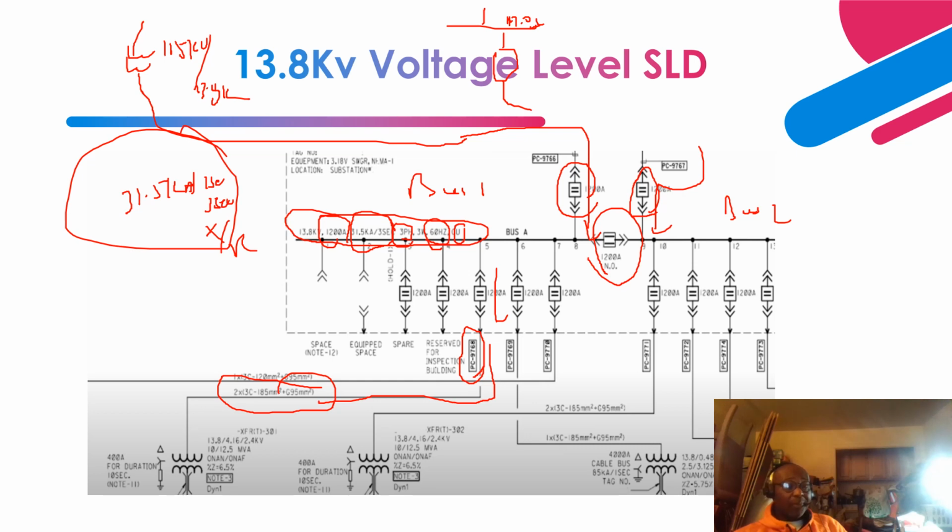So that's the identification of the cable, and this is the mix composition of the cable. All right. Then before it comes to this step down transformer, right? This step down transformer has a delta wound on the primary side, and on the low voltage side is a Y resistive ground transformer, right? Okay, and this is the rating of the transformer. It's 13.8 kV, 4.16 kV, or 2.4 kV, right?